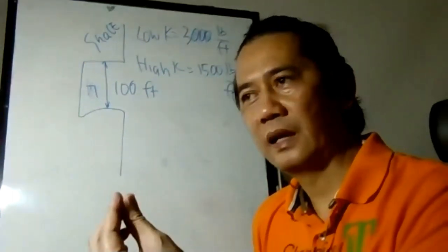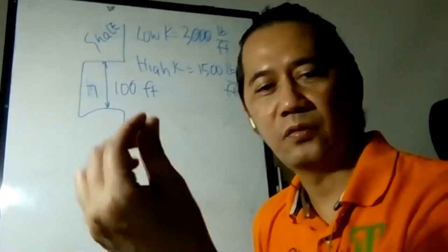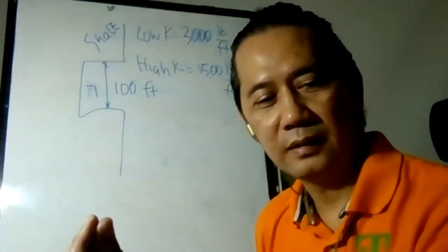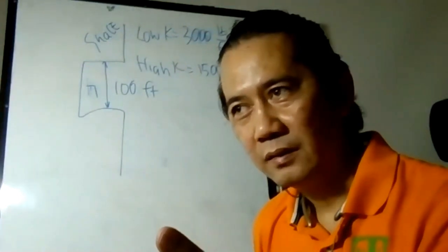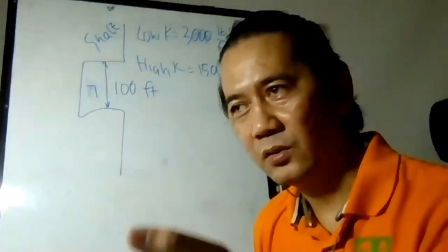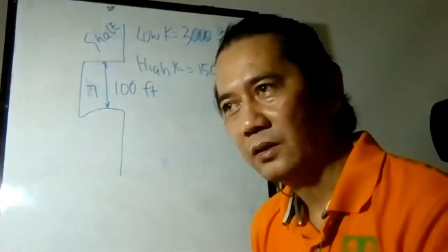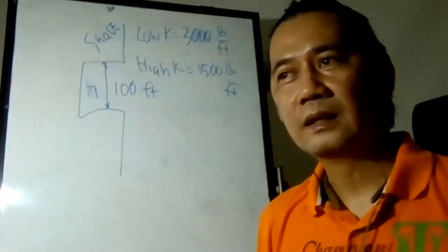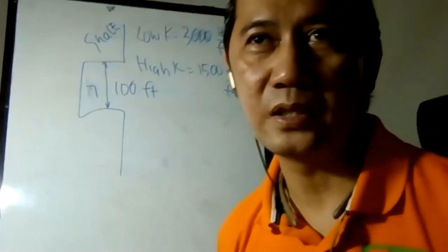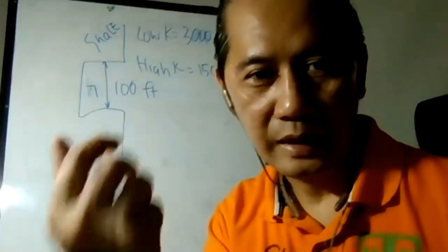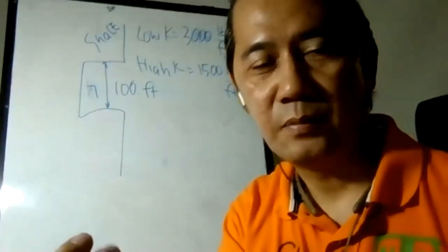Because it's light, you don't need a very viscous fluid to carry this proppant. So you need less viscosity to bring it, and then you can go deeper into the formation. When you don't need a lot of viscosity in a frac fluid, that will help your operation. It will be less pressure, less damage, because the gel that you are pumping is going to be less too, right?